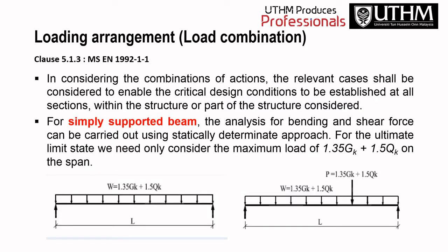So for the loading arrangement here, according to clause 5.1.3 in MS EN 1992-1-1, you can refer to the Eurocodes, okay. So in considering the combination of actions, the relevant case shall be considered to enable the critical design conditions to be established at all sections within the structural parts or parts of the structure considered. So for simply supported beam, the analysis for bending and shear force can be carried out using statically determinate approach.